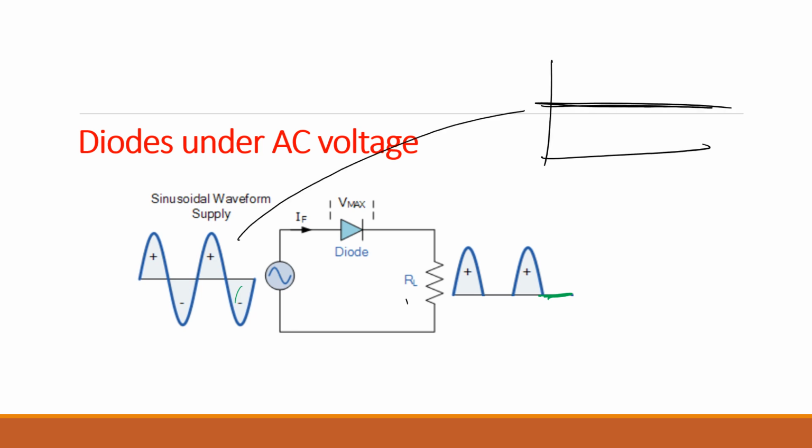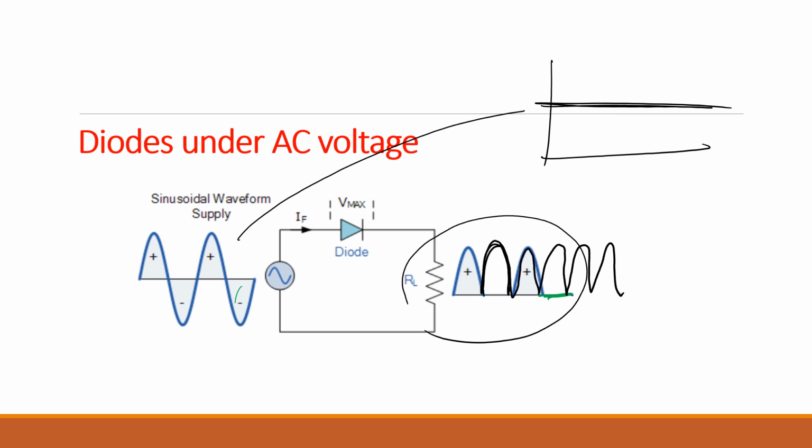So this is on the way. If you can make this, we call it half wave rectification, because you only see a peak for half of the cycle. Sometimes we can arrange the diodes to get full wave rectification like this. We are going to look at it in the next slides. Then this one can be converted to DC. To do the rectification, one of the elements that we can use are diodes. Do you understand? Okay, let's move to the next one.